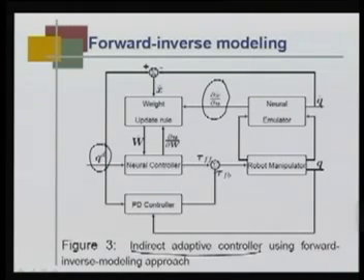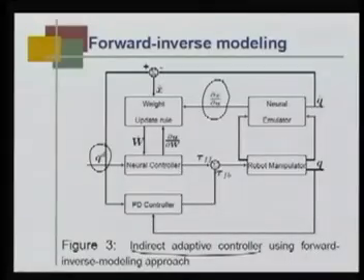And then the neural controller predicts the forward torque necessary for making the robot manipulator exactly follow the trajectory. Now we will show you how we design a weight update rule for this forward inverse modeling, such that the total feedback control system here is Lyapunov stable.